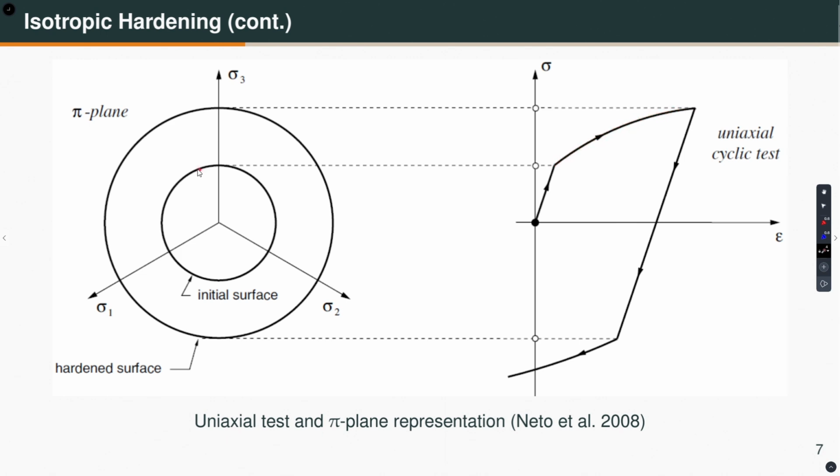So, this yield surface is growing, and let us say at some point it is this. So, you go up to that point. Now, depending on what kind of nonlinear isotropic hardening is used, for example, I will show you the isotropic hardening where this is kind of fixed. So, it can go only up to that, it cannot go past that point.